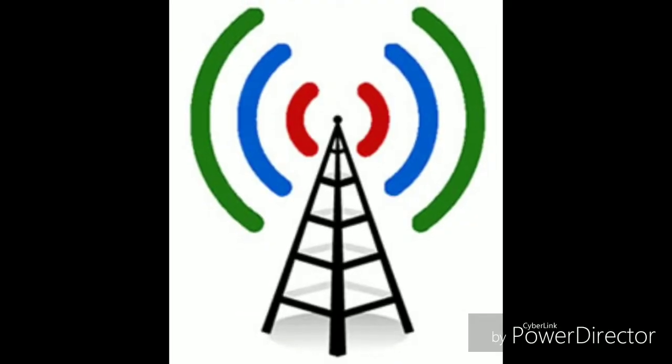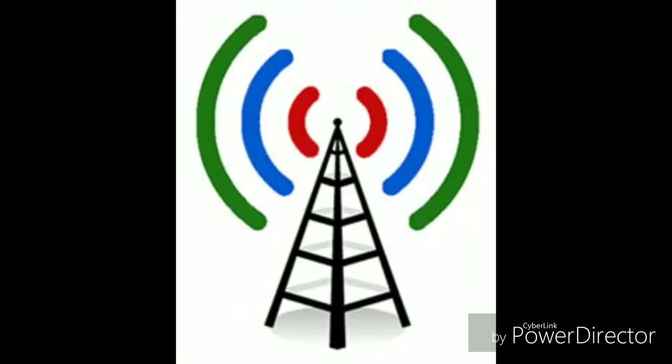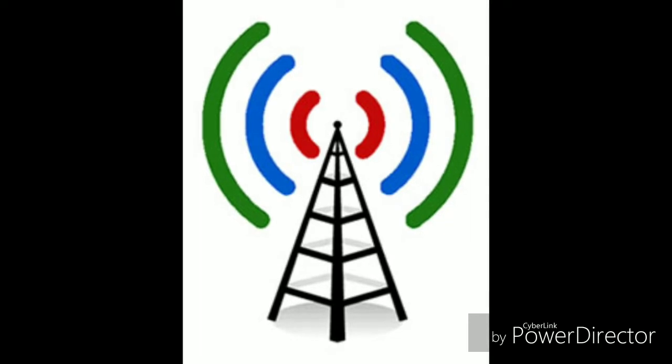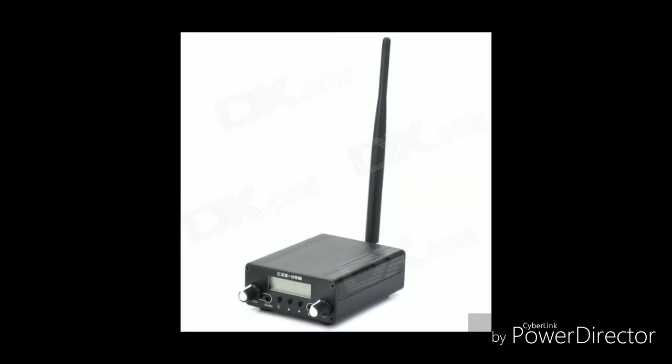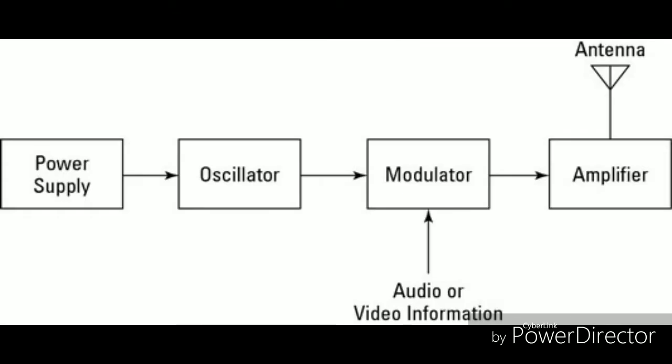Now we see about radio transmitters. A radio transmitter consists of several elements that work together to generate radio waves that contain useful information such as audio and video. Power supply. It provides the necessary electric power to operate the transmitter. Oscillator. It creates alternating current at the frequency on which the transmitter will transmit. The oscillator usually generates a sine wave, which is referred to as a carrier wave.